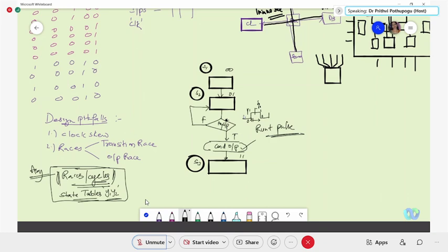Maybe your system will be landing in a new stable state, because this is the iteration path, and within this we are saying before the clock goes from 1 to 0, it has to complete that iteration. So by nature, this iteration will complete and make the system go from S2 to S3, but because of the shorter runt pulse type of asynchronous input happening, it is not giving sufficient time to evaluate some conditional output.